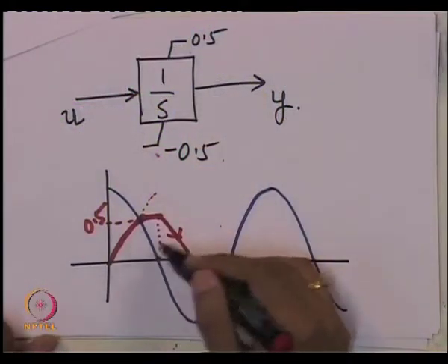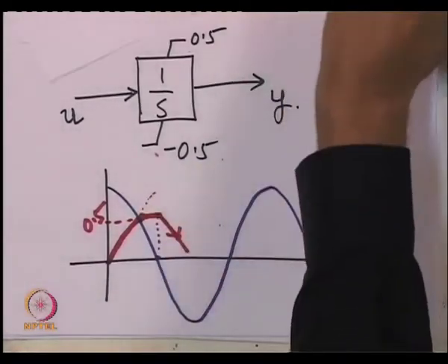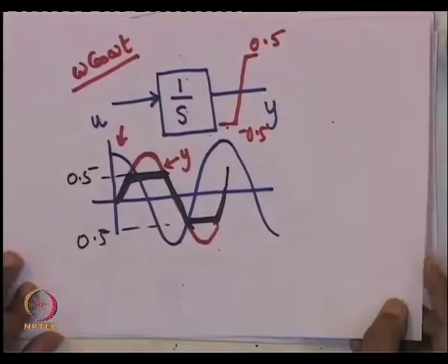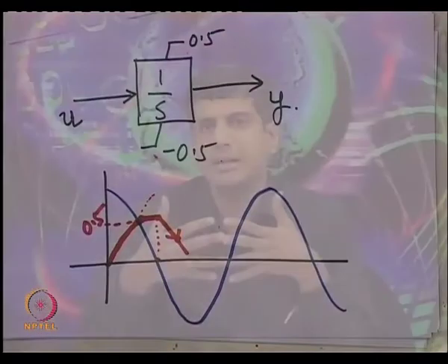Okay. So, this is what happens in case you have got a hard limit. In fact, if you have got a soft limit, it is this, and a hard limit, it is this. So, whenever you have got an integrator which is hard limited, you will find that it stops integrating as soon as the hard limit is hit. In fact, this is desirable under certain circumstances.